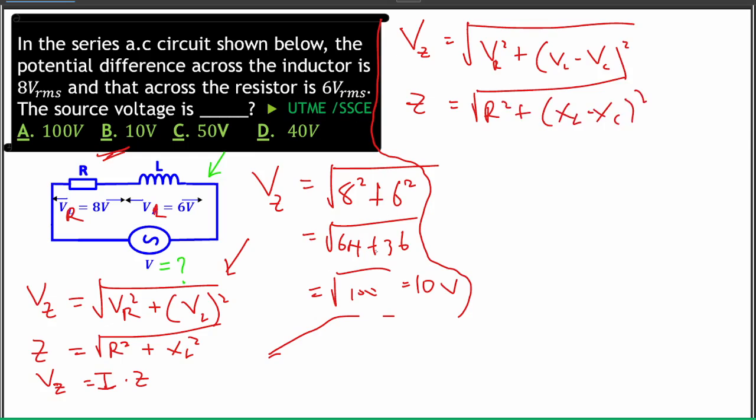Now you remember when we handled pure resistive circuit, pure inductive and pure capacitive circuits, all right? We saw the concept of phasor, and we said a phasor is just a rotating vector used to describe any of the AC quantities, whether current or voltage. Okay, so if we establish the three vectors we have using VR as the reference one, it will be pointing in the positive x-axis direction, all right? That's along the positive x-axis. So VR, since it is in phase with the current, all right?